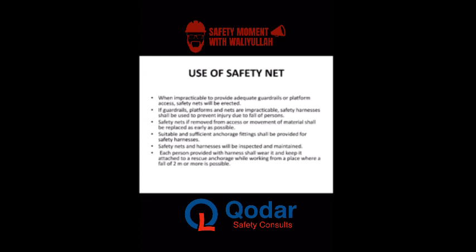We also want to use a safety net. These safety nets, when it is not practicable, or we see that we cannot use a guardrail, that is when we employ a safety net. And safety nets, if damaged, should be replaced immediately. The safety net and harness should be inspected and maintained thoroughly.